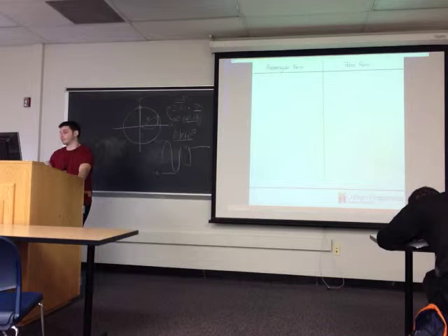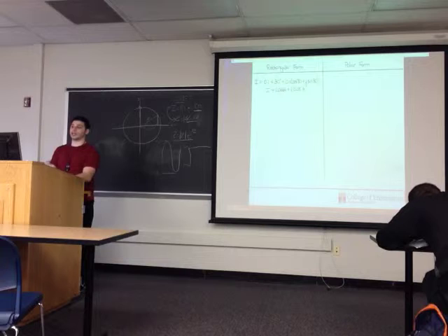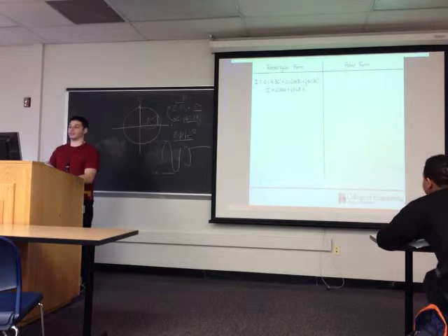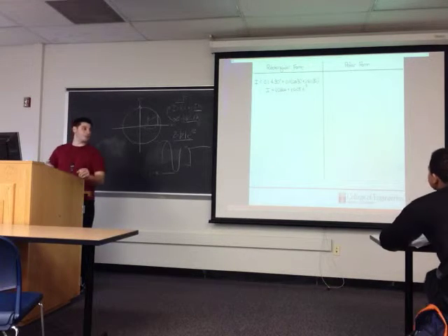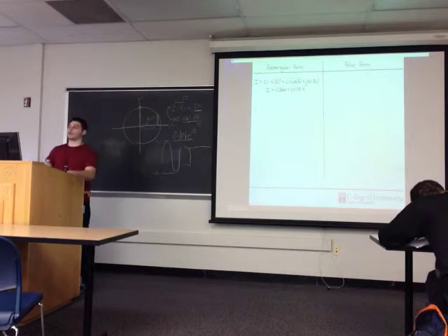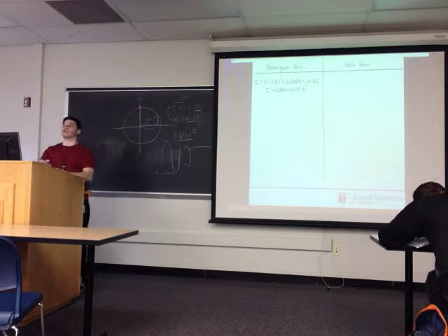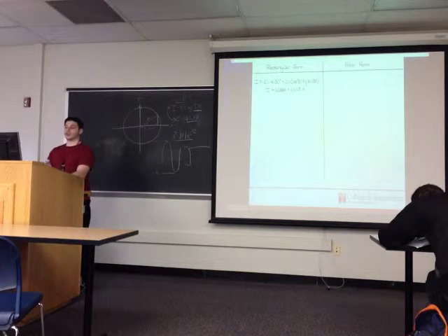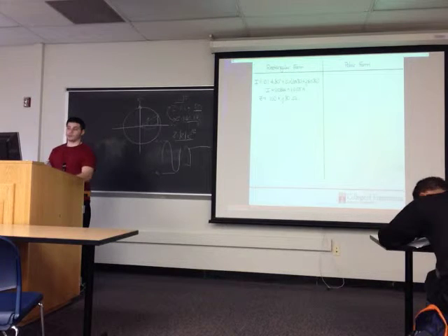They might do both. Okay, so I is equal to 0.1, which is the magnitude, times the cosine of the angle plus J sine of the angle, right? From one of those early slides, we gave the equation for converting from polar to rectangular. So now we have I as this and Z as this. What do you think we're going to do to both in rectangular form?